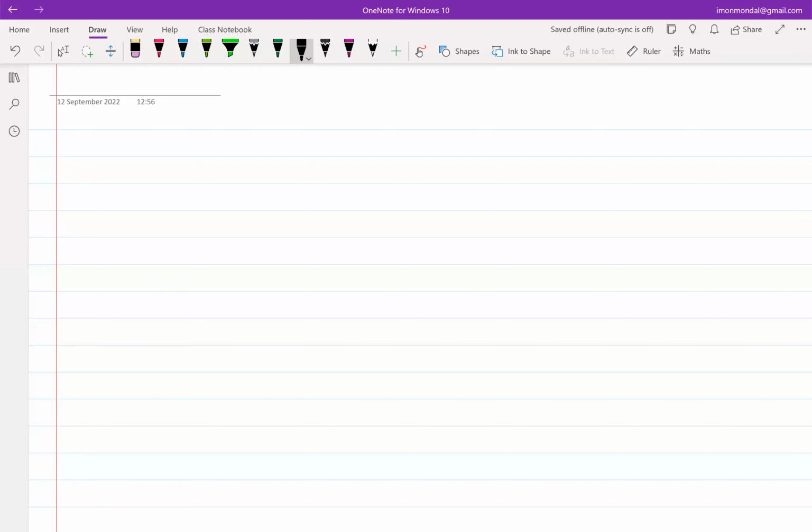Which includes MOSFETs. So now when you have MOSFETs, we know that MOSFETs cannot operate in all regions of operation, which means you'll have to ensure that the regions of operation of the MOSFETs are where you want, which in our case is on and in saturation.